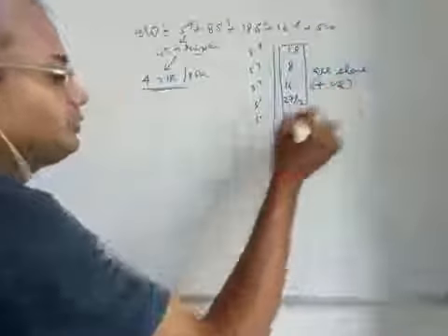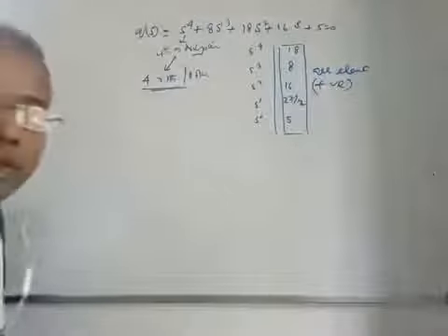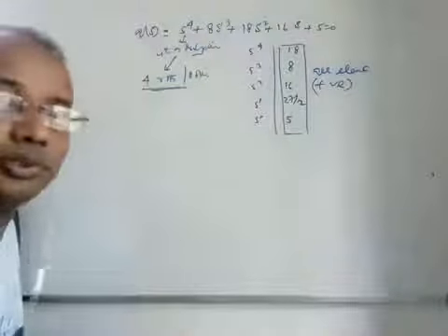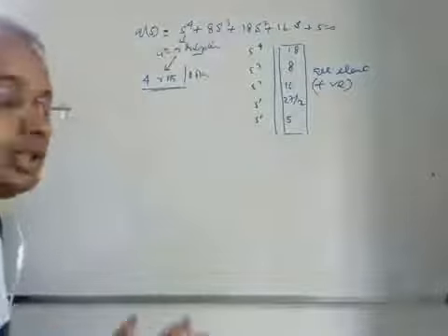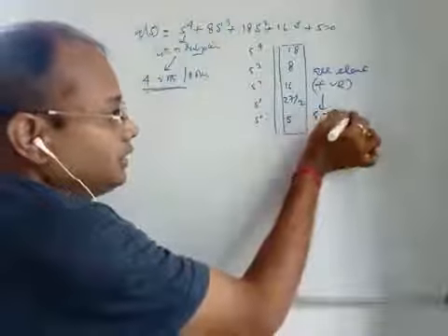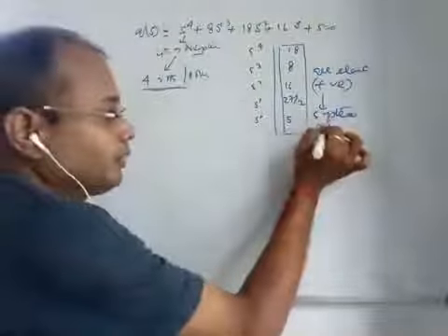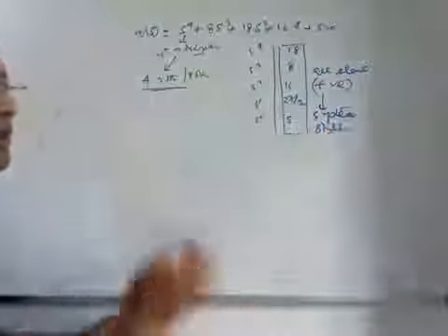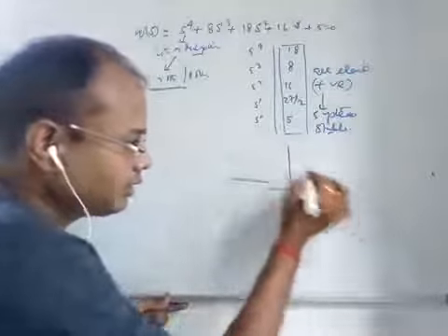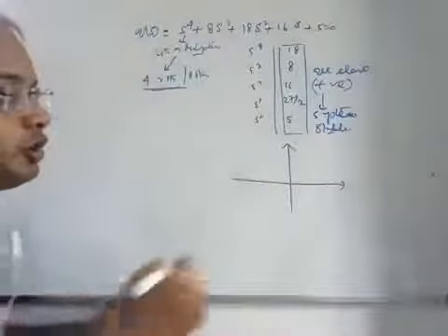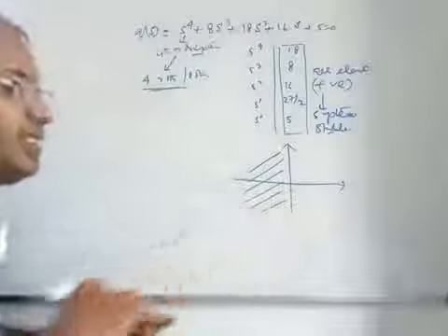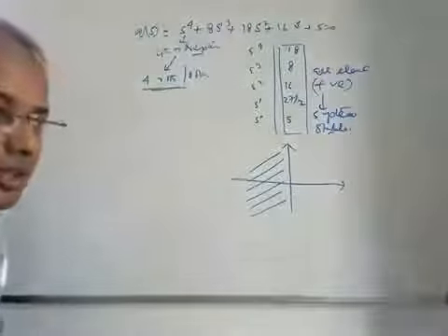are positive. So according to Routh stability analysis, if all the elements of the first column of the completed Routh array are positive, the system is stable. System is stable. And if the system is stable, then from the generalized rule, you know all the poles are on the left hand side of the S plane.